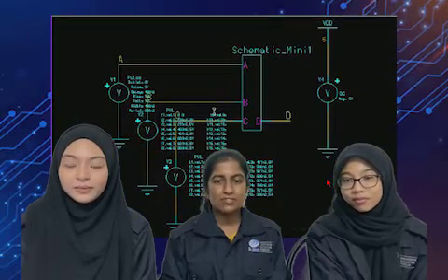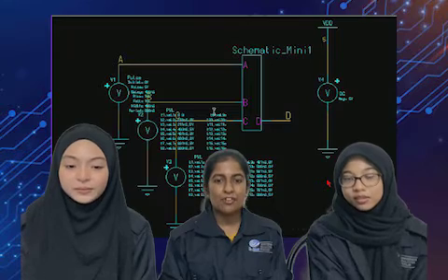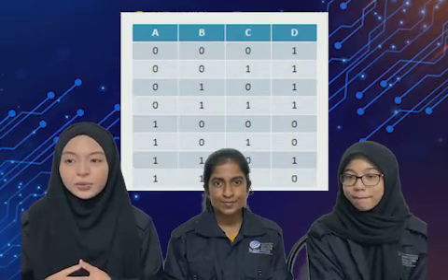After that, we generate the schematic symbol, which connects to the CMOS transistor, to identify the correct output waveform. As we know, the symbol is used to obtain the output waveform. Our output waveform, as you can see, is the same as the truth table that we produced. Next is to design the layout. The layout is based on our Euler path and stick diagram. For more information about it, we're going to continue with Munir and Fakrul.